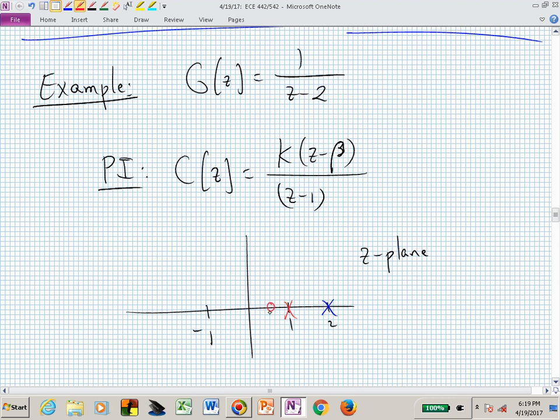for some reason it didn't like that. So let me try it again. We put it here. These two go together. We have the geometric mean again, determining our radius. And what are we wanting to do? We're probably wanting to crank up the gain such that we get inside that unit circle. That's what we want to do for this PID controller.